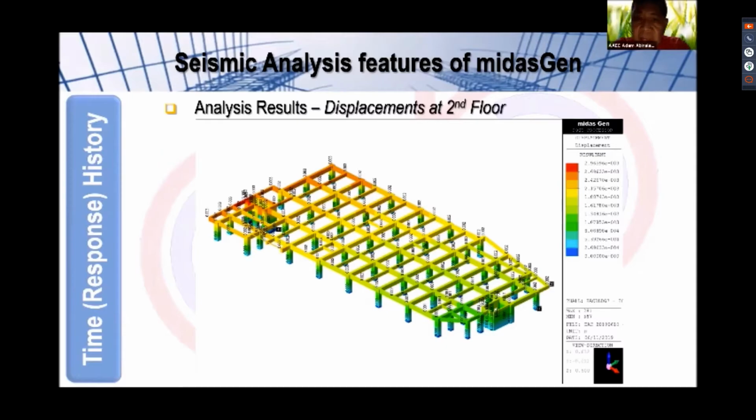Then, of course, we did the run. Oh, by the way, when we did this modeling, you have to prepare two models. One considering the time history ground motion data, and the other using the response spectrum. You cannot input these two earthquake data in one single file, since you will have to run them one at a time. So what we did is we prepared two models.